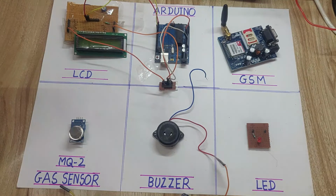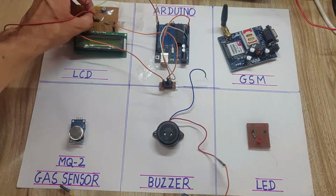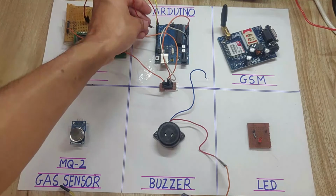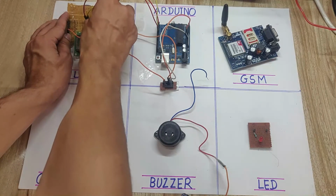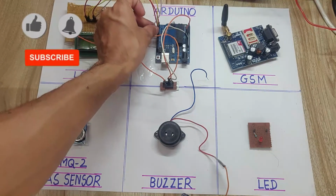The next pin is the D4 pin of this LCD, which should be connected to pin 6 of Arduino. So connect the D4 pin to pin 6 of Arduino. Now the next pin is the D5 pin of LCD, which should be connected to pin 7 of Arduino. So connect the D5 pin to pin 7 of Arduino.